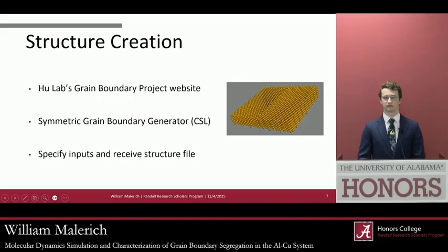Over what timescale are these simulations conducted, and how do you know it is long enough to recreate experimental results? Yeah, so the time step for metals in LAMMPS by default is 1 femtosecond, and we run these on the order of 2 million femtoseconds, which is not a very long period of time, but the simulated samples are not very large. They're only a couple hundred nanometers across, and we know that they're similar to experimental results because they achieve equilibrium at a certain point and stop changing.